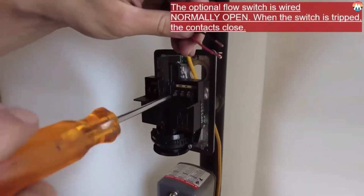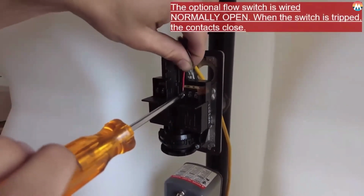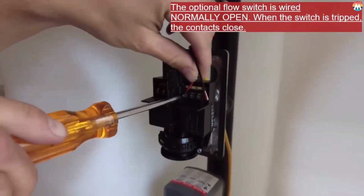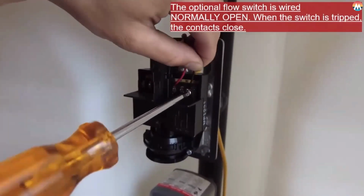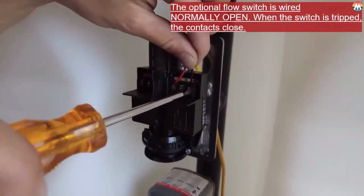If the home hydrant has been ordered with a flow switch, now's a good time to hook that up. These are connected normally open, meaning that when the switch closes, the alarm rings. Typically, you would have some type of watertight fitting in the back of the flow switch, but for demonstration purposes today, we are just hooking it up quick and easy.